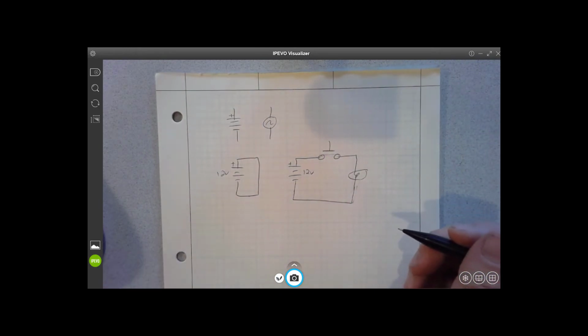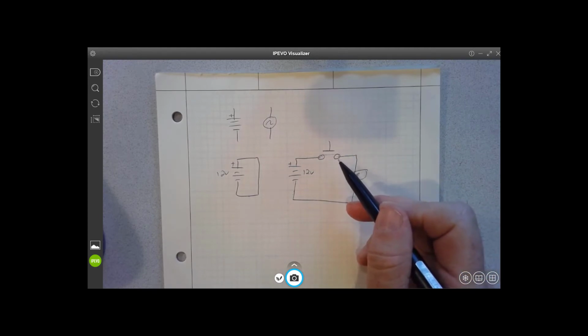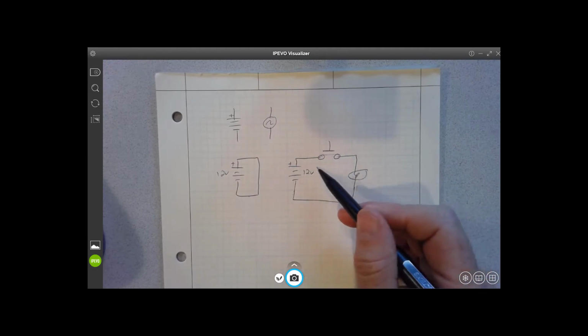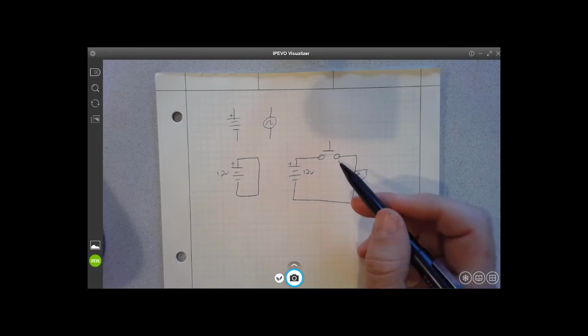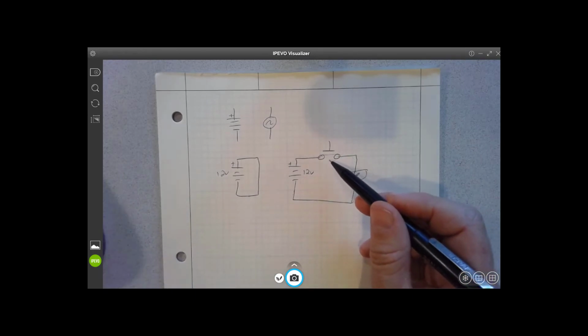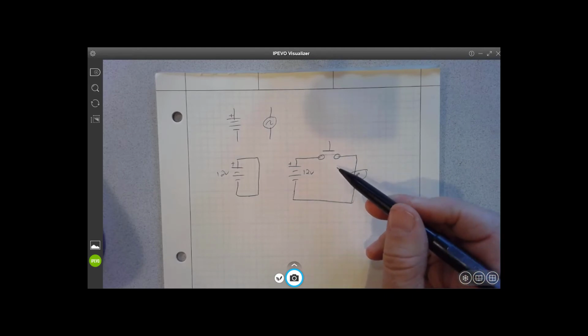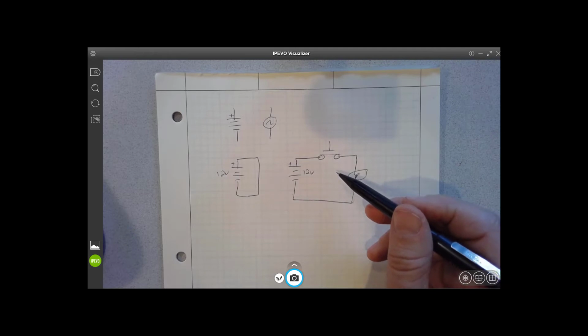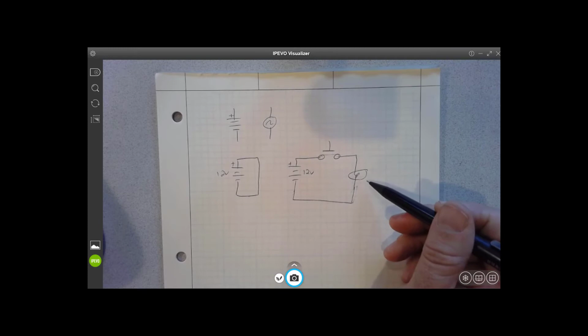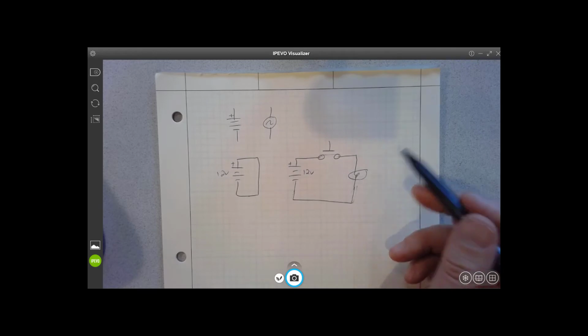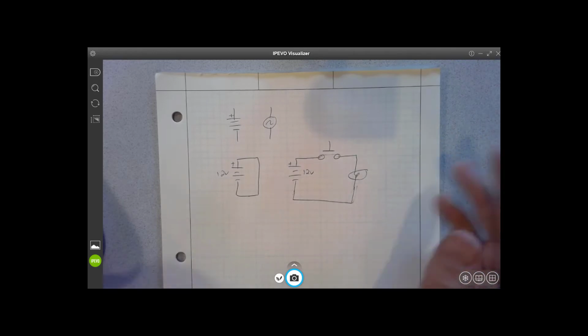Obviously, there could be lots of different input devices. If you remember back to MEC 133, float switches, pressure switches, selector switches, limit switches. Those are all mechanical devices in general. The inputs could also be an electronic device, like a proximity sensor, a photo eye, ultrasonic sensor, that kind of thing. Again, same thing with our outputs. I just had a lamp here, but it could be anything: a control relay coil, motor, starter, any kind of output potentially.